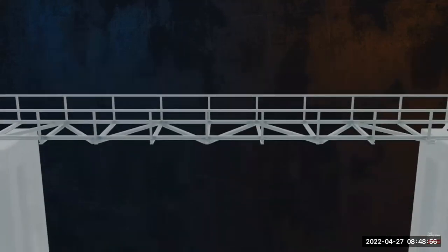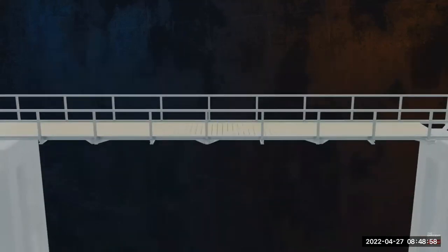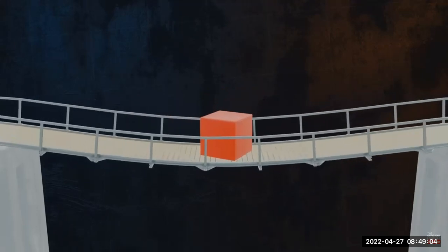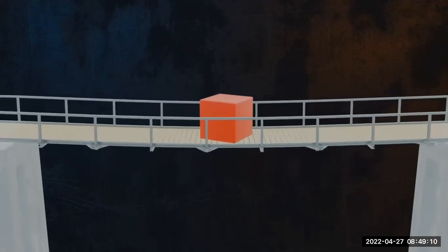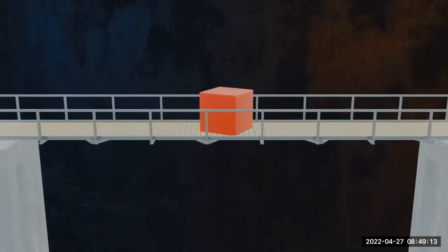Take the example of a bridge. If we construct a bridge from a material with a low Young's modulus, it will deflect a large amount when something crosses it, which is probably not the desired response. Selecting a high stiffness material would ensure that elastic deformations remain small for large loads.